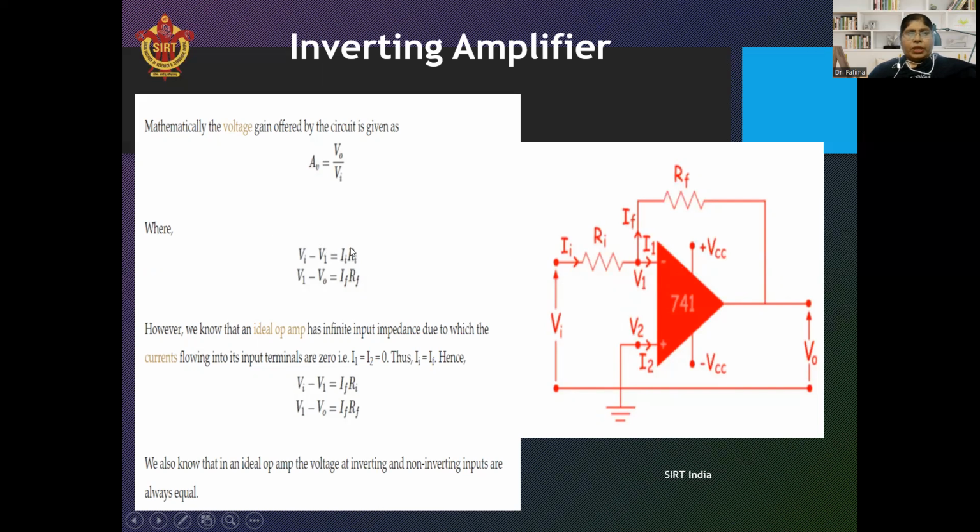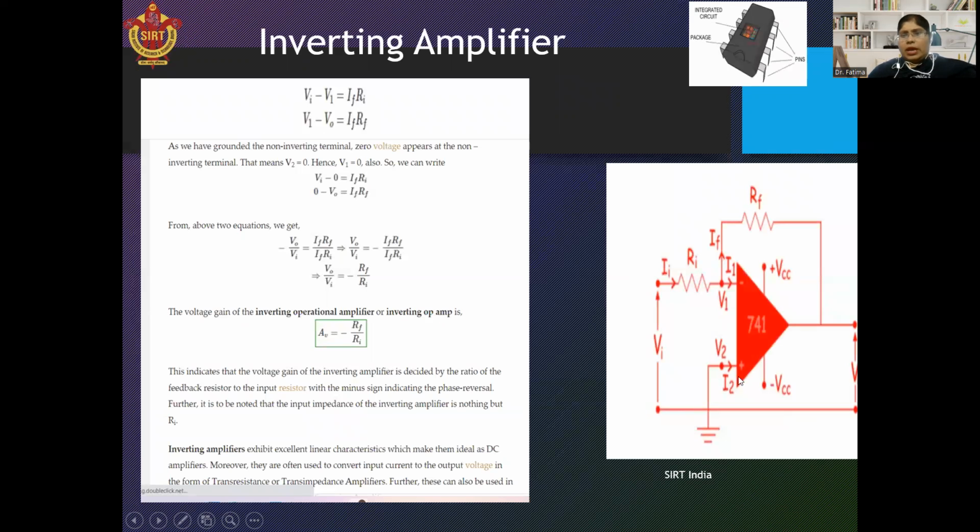Here it is written. Now replace this Ii by IF. So here the equation is written. This Ii is replaced by IF. This equation remains the same. Now see, as we know that in the inverting amplifier, the negative terminal acts as a virtual ground. So V1 is equal to 0 since V2 is equal to 0. So put V1 equal to 0 in these equations. So now this is the equation. Now you can see Vi is equal to IF Ri and minus V0 equals IF RF.